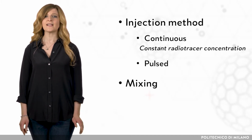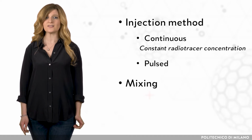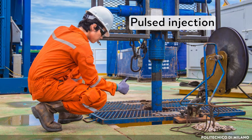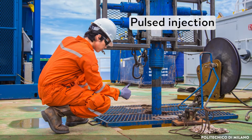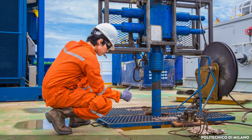In this case, the injection could even last over a year. The tracer concentration at the detection point is compared to the concentration at the moment of injection. Pulse injection is used in oilfield reservoir tests. In this case, the injection time could take up to several hours, but it is shorter than the time needed for the radio tracer movement between injection and detection.